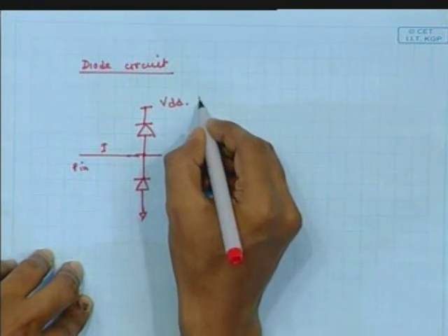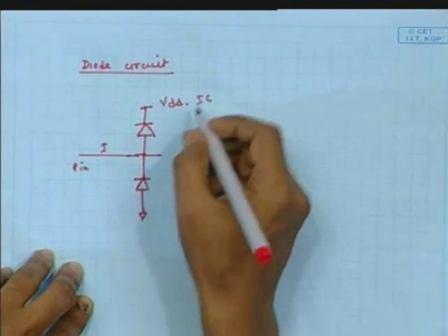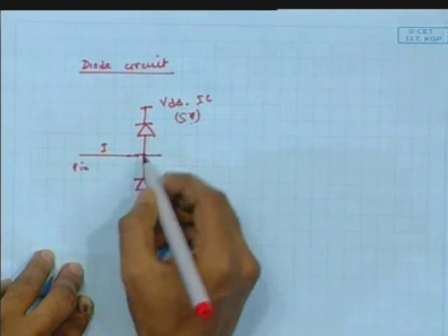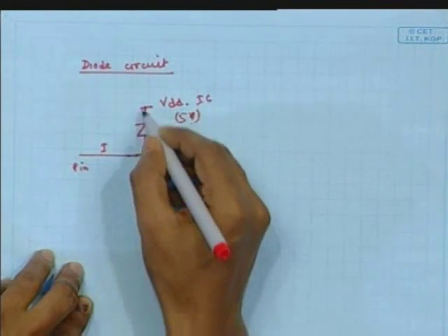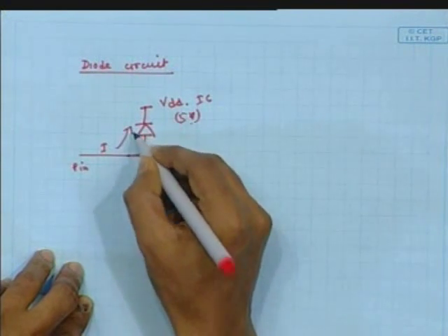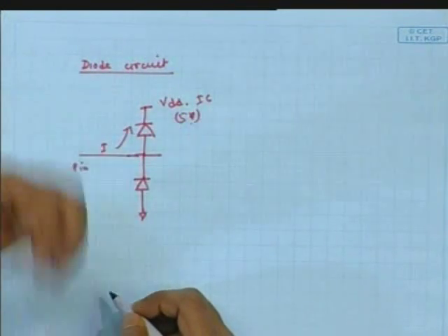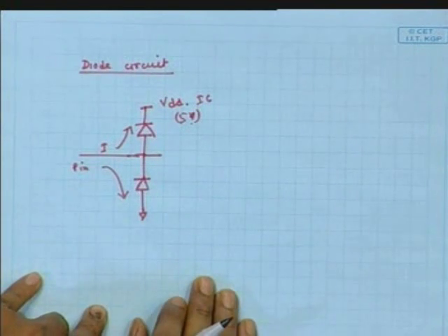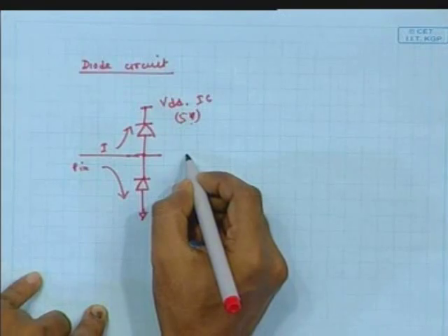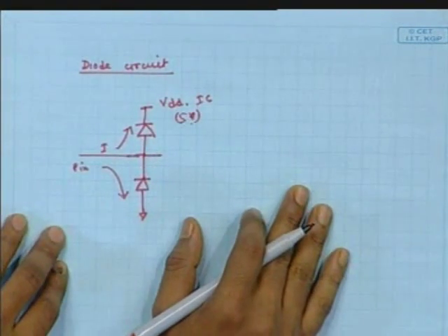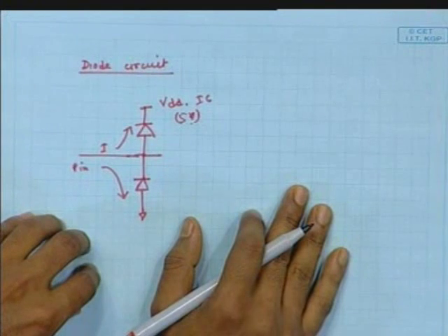This is the VDD of the IC. Consider this is 5 volt. Okay. So if a high spike comes, when the spike is more than 5 volt, this diode will turn on and will discharge through this path. When the spike is lower than ground, then it will discharge through this path, right. So here you can see it will be maximum 0 to 5 within that range, it will not be more than that. This is a very standard diode scheme, okay.